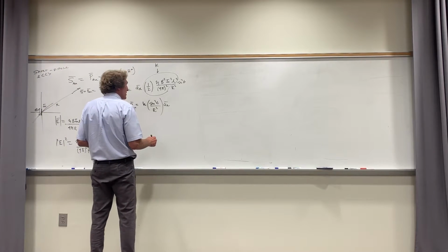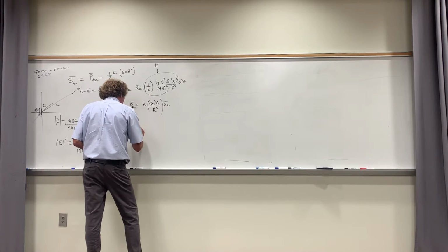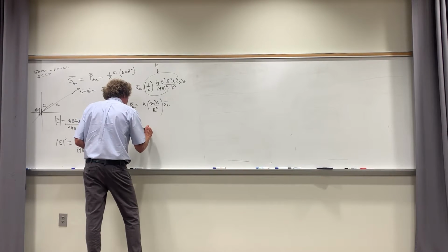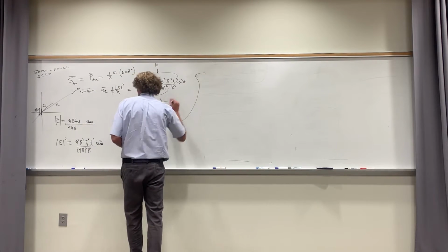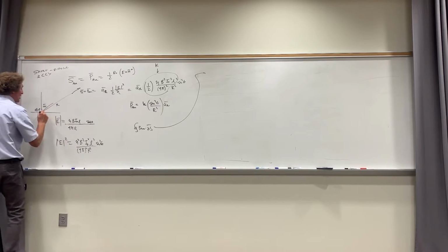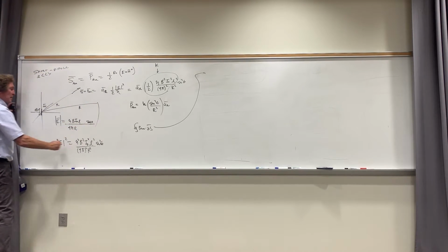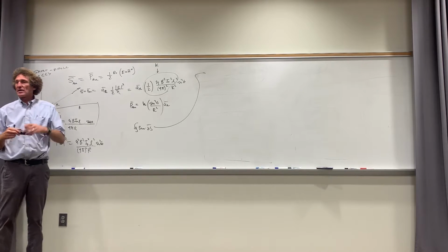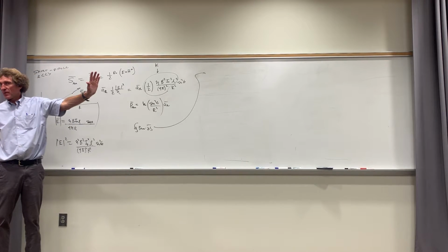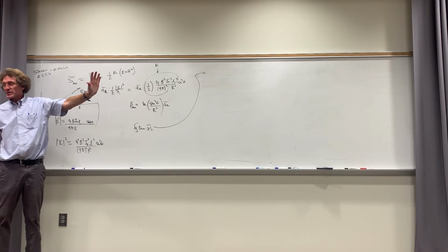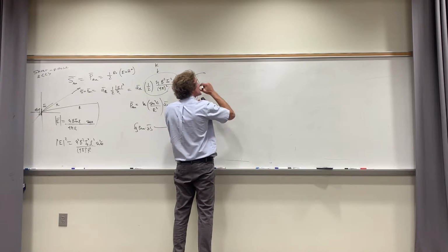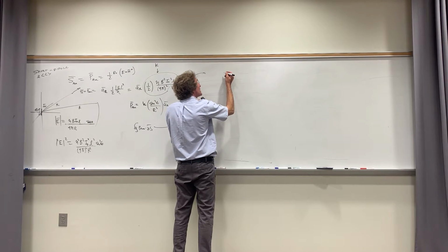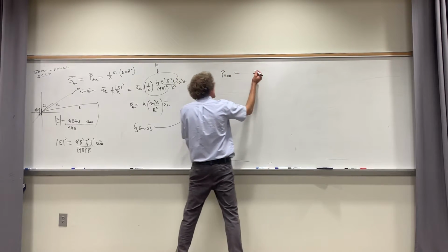So now our next step is this. We're going to take the integral of P av over dS, the surface of a sphere. It's a closed integration. For that, I'm going to go up here. So what I do is this. I go a long ways away, and I put a sphere around there, and I want to calculate all the power radiated from that antenna. Are you with me, everyone? This is very important. So the total power radiated from my antenna, and what should I call this? I don't know what he calls it. How about P rad? Is that what he calls it? Yep.